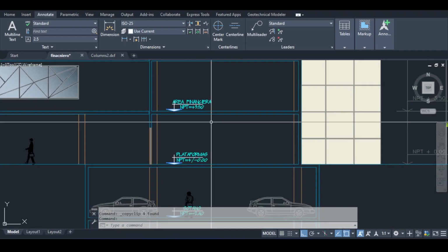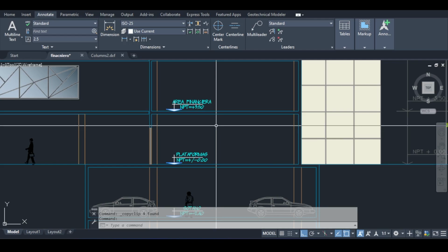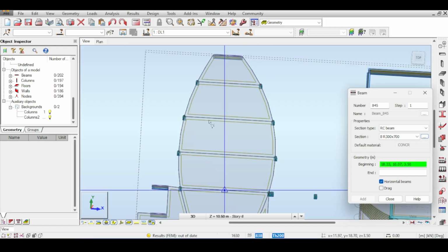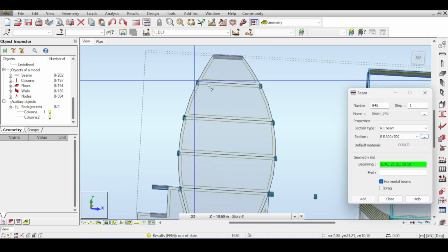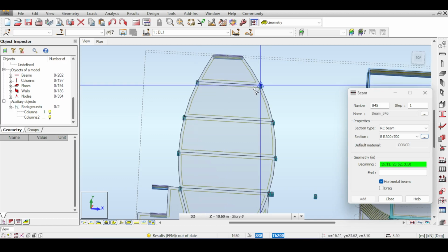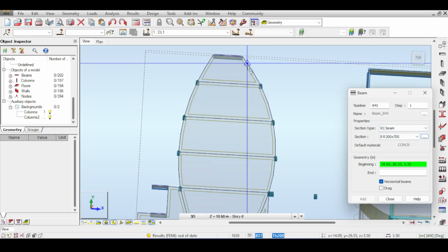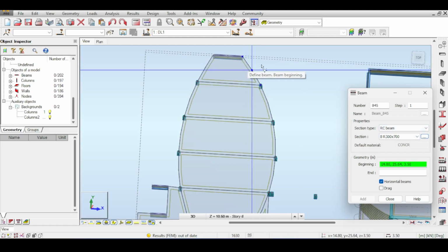the future. Okay, now there is something I want to talk about very quickly. This is something that the beginner engineer falls into. I know you have codes, and I know that the easiest way to deal with those things is to go to your code. For example, the ACI code says that if you have a span simply supported, although it's going to be a frame, but if you have a span simply supported, then the height of the beam is L/16. And you just calculate this and assume your thickness to be in line with the recommendation of the ACI code, and that's it. Now, this works fine usually.